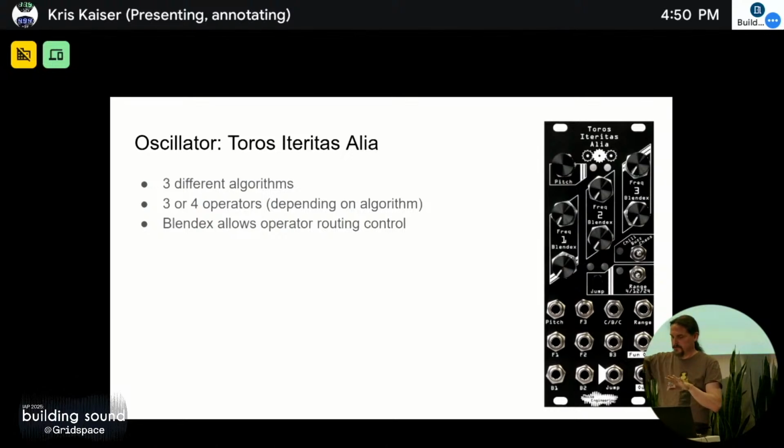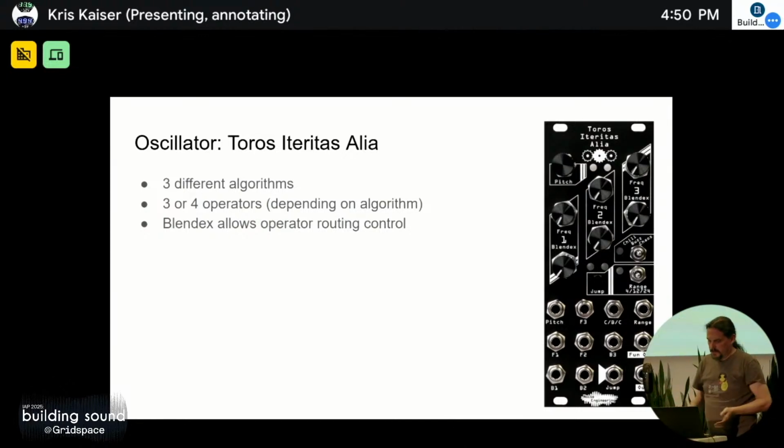Phase-wise, it'll do a full 2 pi across the range, and then you can place where you want the halfway point. Those are all biquads, which is a kind of filter implementation. So that's a pretty normal, simple filter to use.